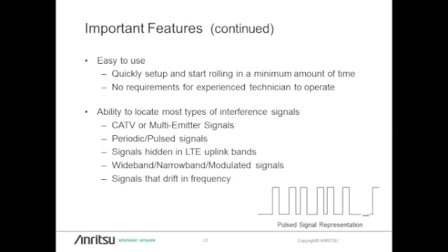You also want something that's easy to use. In this system, the setup is typically less than 5 minutes, and most of these settings are remembered. So if you want a certain RBW, resolution bandwidth, or video bandwidth setting, or if you need a preamp, you keep that on. You turn your spectrum analyzer off, you turn it back on the next day, and your settings are remembered.